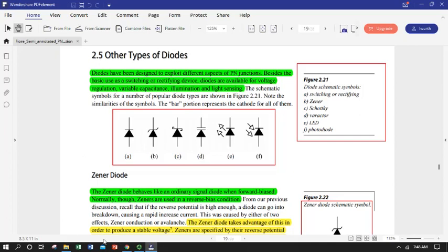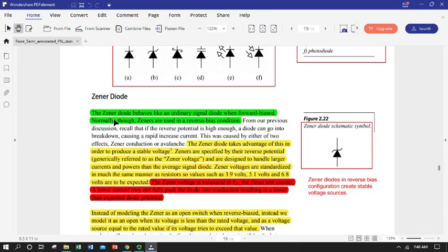Okay, so we're going to start with Zener diodes, and that is circuit schematic B here. So the essence of a Zener diode, it is the one and only diode that can be operated consistently in reverse bias without ruining it. It's designed to operate past its reverse breakdown. So it doesn't hurt it unless you go past its maximum reverse limit. It has limits like anything else, but it is literally intended to operate mostly in reverse.